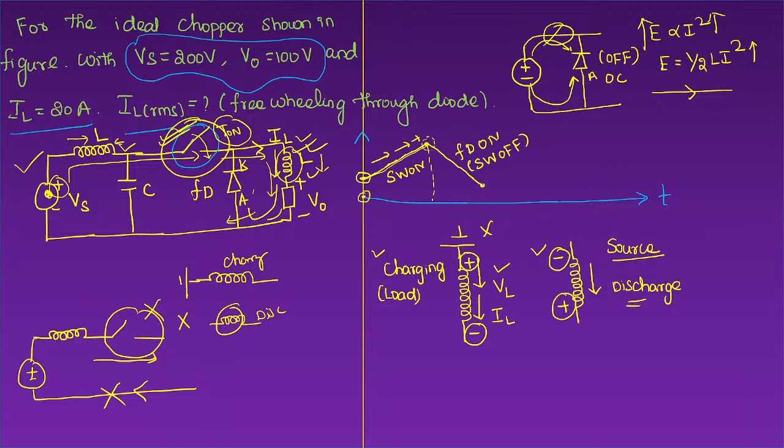So it will go down to a certain minimum value. I told you the residual property of the inductor will not make the inductor energy zero. It will maintain a certain minimum value. From there again, this is one cycle. The on time period is basically the conduction period of the thyristor. So this switch is on up to this point, that is when the inductor is charging up to its maximum value. In the off period, current is freewheeling only through the freewheeling diode and the energy keeps on decreasing because the energy is getting dissipated through the load.